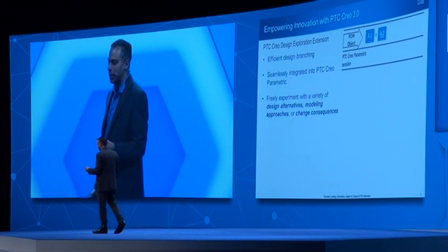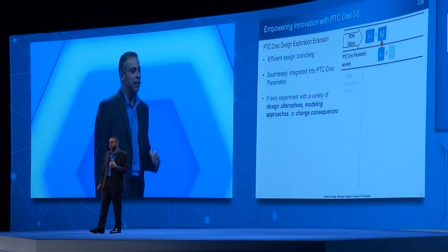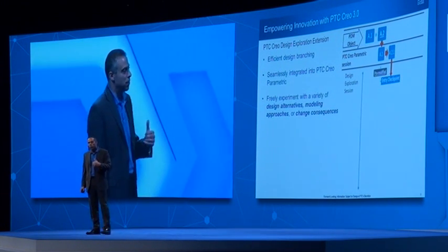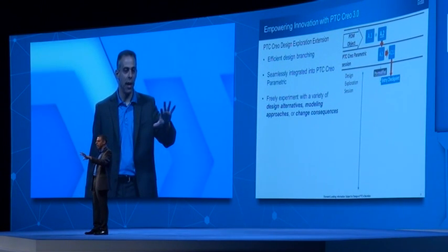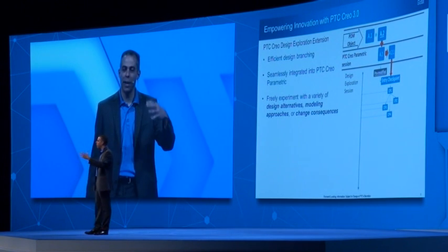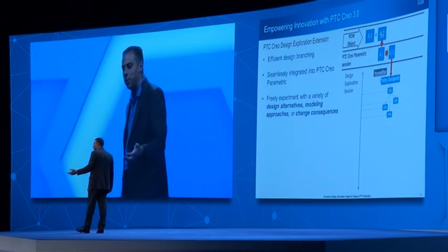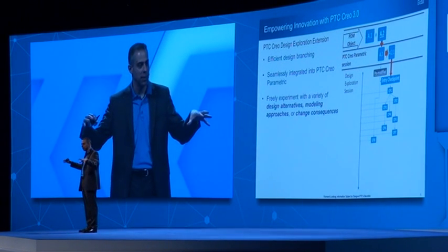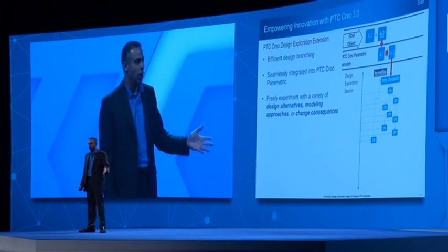Graphically, the way it works is like this. Your object is moving along in the PDM process. You finally decide, I gotta make a change, and you enter a design exploration session. We save a checkpoint to get started. And from there, you can start doing work. And if at any point in time you like what you've done and you think this is a good point to save, you just save a checkpoint and you move on. And you can build checkpoints off of other checkpoints. Like I said earlier, as deep and as wide as you like to go, you can go.